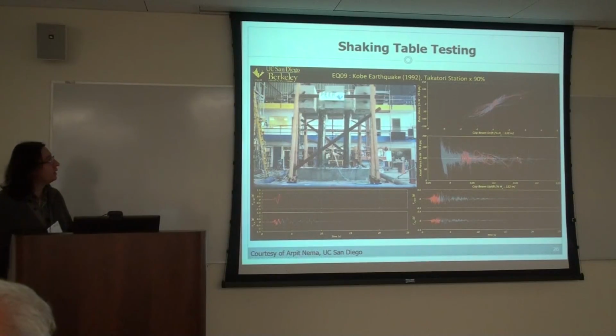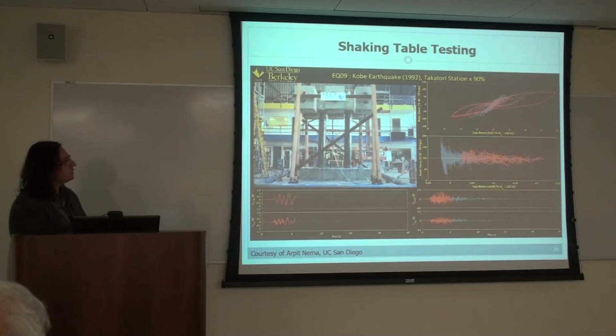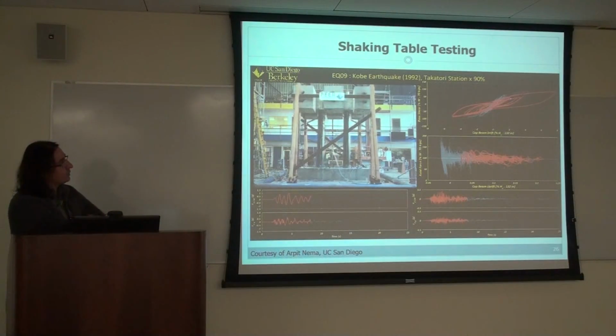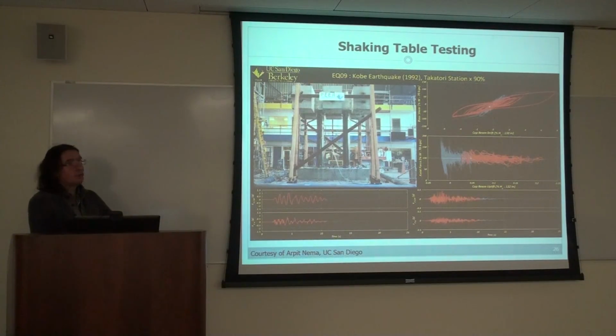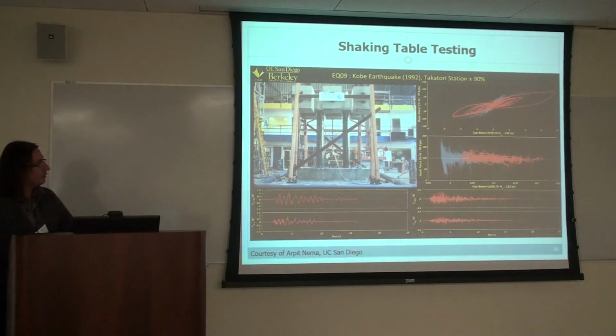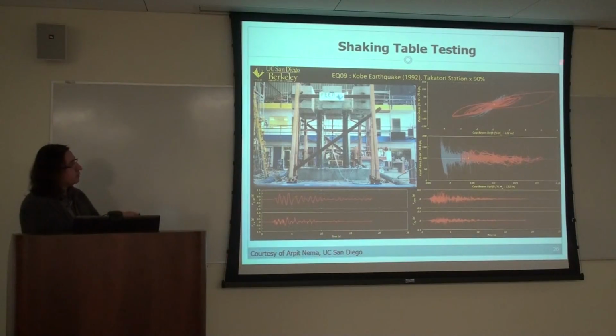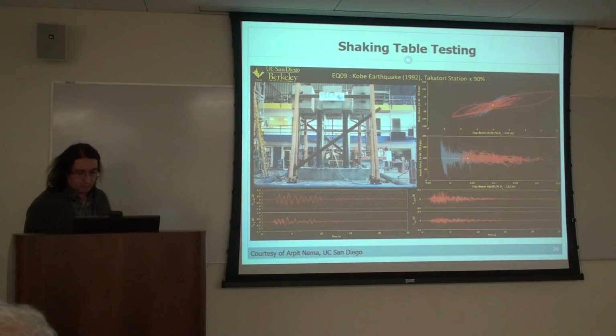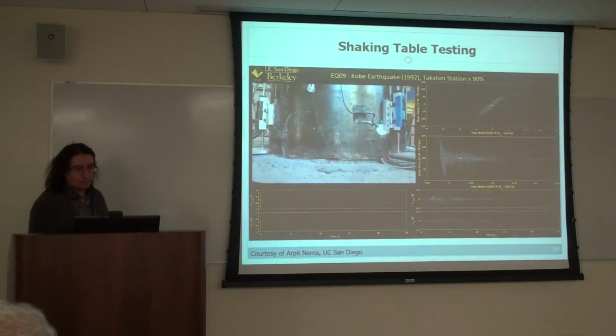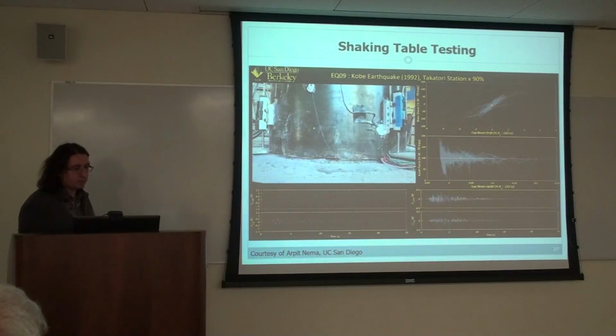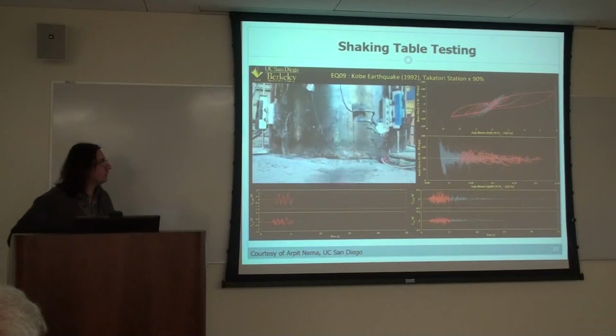So this, actually you can see one of the large tests, and then you can see really large drifts, and eventually the column comes back to the center, so it's self-centering. And here you see the force displacement, you see the energy dissipation plus the pinching type of thing, which is actually the self-centering. And this one is a similar video that just shows the rocking from the column base. Again, Arpit prepared these. You see the rocking.